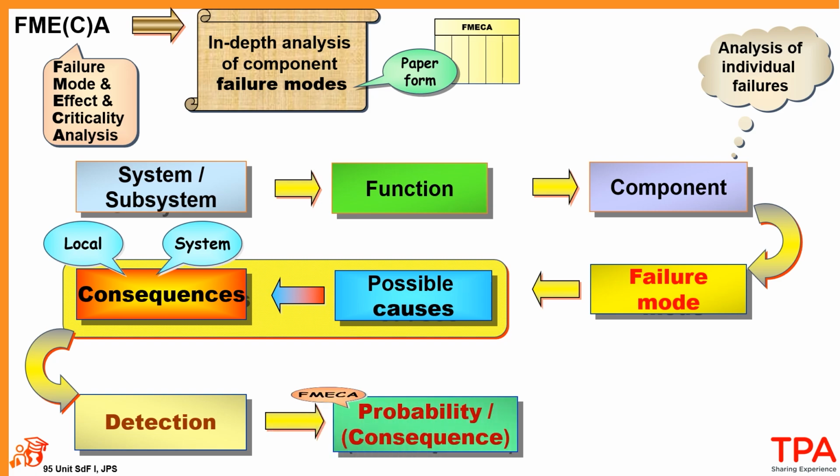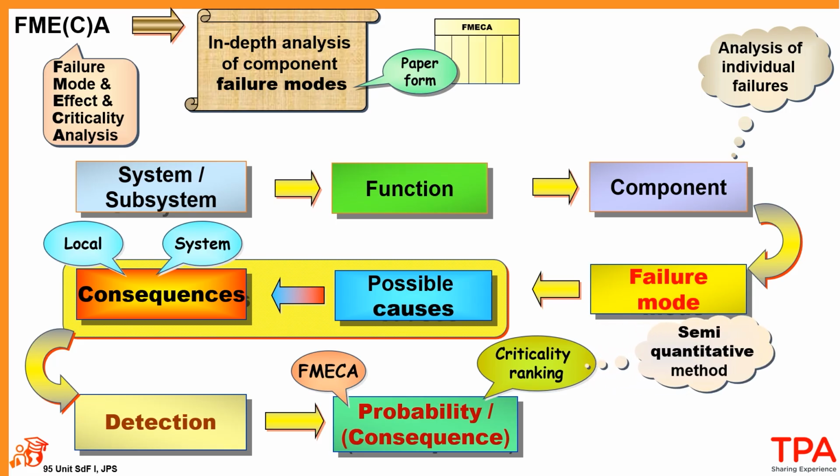The originality of this approach is that it is possible to mention the probability and the level of consequence of the failure mode under study. This is the so-called criticality analysis. This allows performing semi-quantitative analyses with this approach. Then, again, the last column is devoted to adding comments when needed.